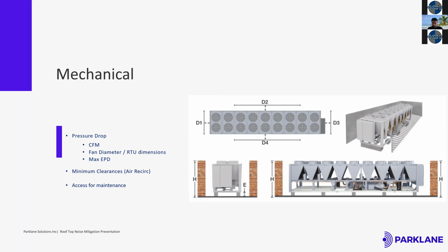And not just that, when you put an acoustic barrier wall, you don't want it to be too close, so that the air for the intake has sufficient gap, or else it could potentially create a recirculation problem. So all of that needs to be considered when you're creating an acoustic solution.